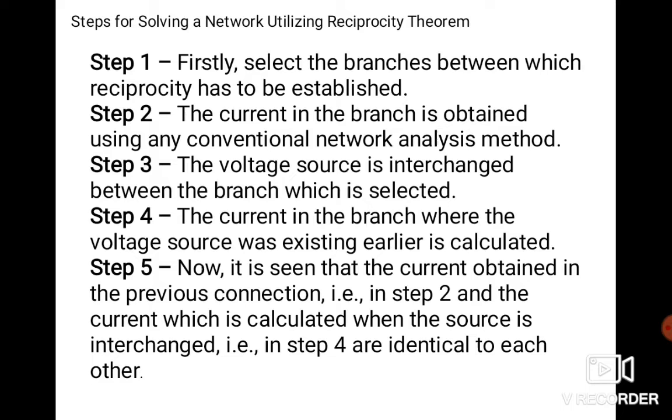You cannot use it with dependent or independent sources. Also, we are considering only the zero state response by taking the initial condition to be 0. In this sense, the theorem is more restrictive than the superposition theorem we have seen earlier. In the superposition theorem, the sources are connected in a bilateral network. So here some restrictions are there.